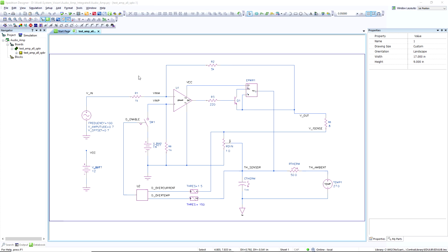So as you can see, it's a fairly powerful, well-rounded tool. We're integrated with the PCB schematic. Got lots of stuff to make that flow nicely, make it easy to set up a design that was originally focused on PCB to get it ready for simulation. Lots of different models that we can support. Specifically, SPICE is used for a lot of the simulation, but for cases where models aren't available or you want to do something tricky, we've got the VHDL-AMS modeling.